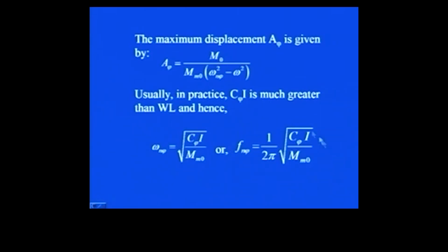So, in this class we saw how we can get a measure of damping using the damping factor in the case of free vibration tests and forced vibration tests, and after that we saw how we can go for the analysis of block foundations. In that we saw that there are basically 6 degrees of freedom, that is translation and rotation about the 3 coordinate axes x, y and z.